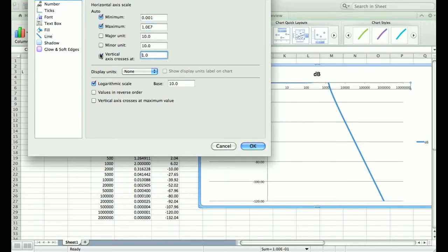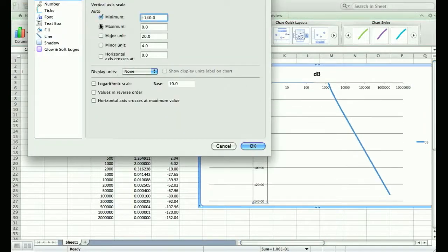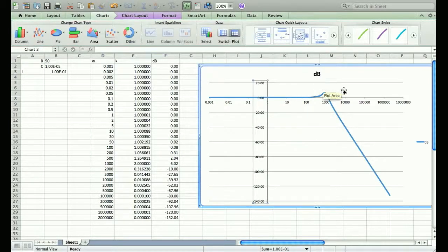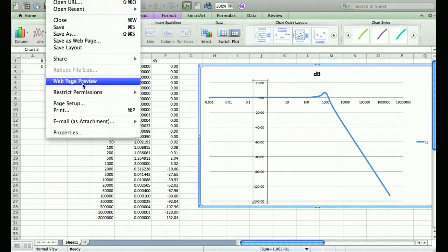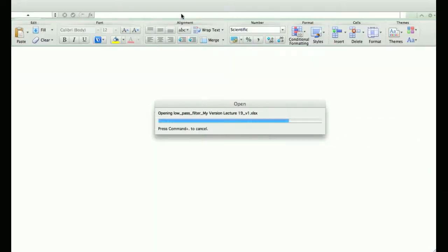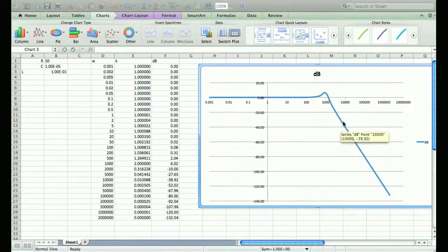Alright. So you can see the red line is what type of circuit? RC. Okay, how do you know that? If there wasn't a legend on the plot, and you saw this plot, how would you know automatically that it was an RC circuit? Because of the slope. Yeah. How quickly does an RC circuit fall off? 20 dB per decade. Okay, yeah. And an RLC circuit? 40? Okay, good. Everybody's been paying attention in lab.